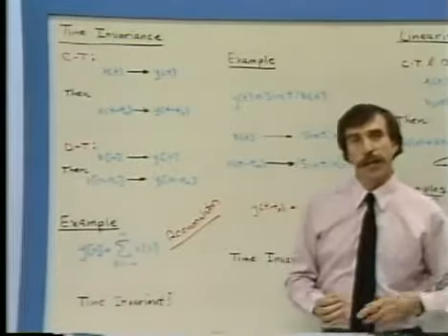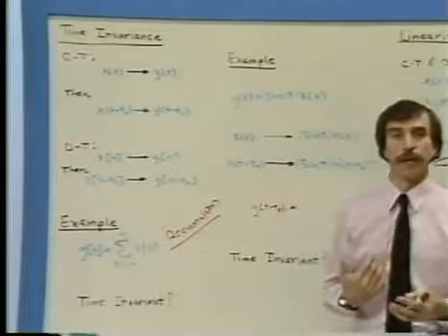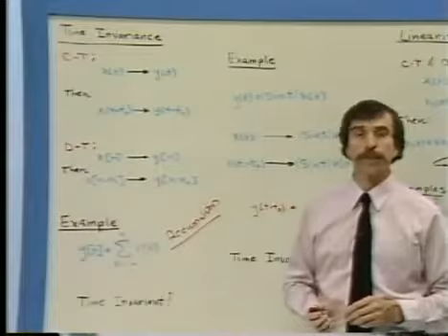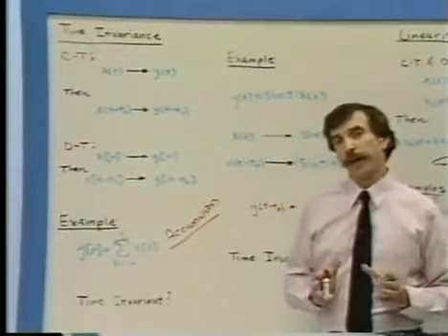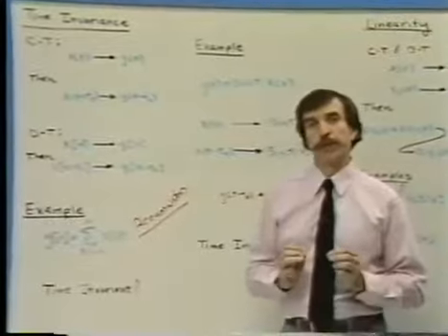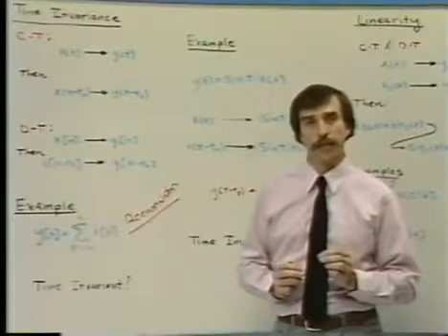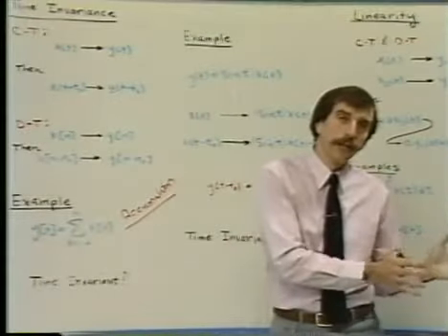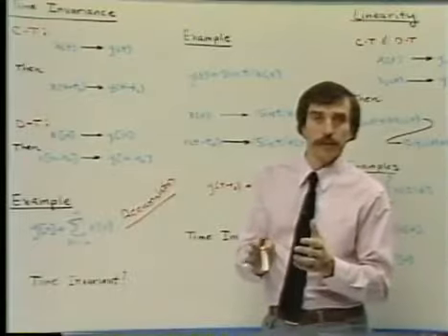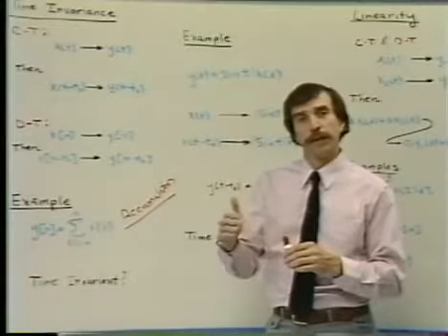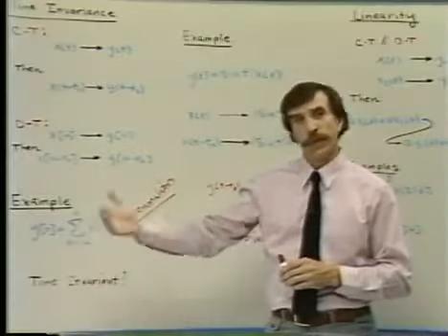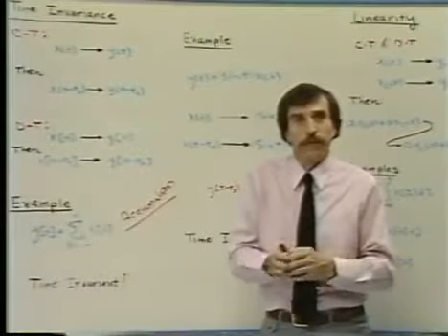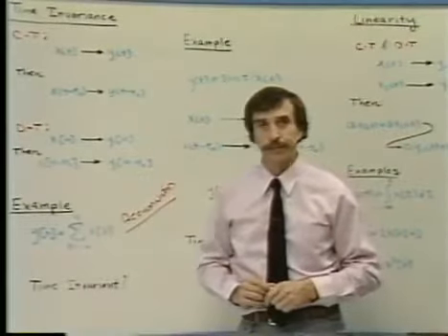The best way to establish that is to work through the equations and verify that it either does or doesn't satisfy the formal definition of time invariance. Informally, it makes intuitive sense that the accumulator is time invariant, because if you delay the values that you're putting into the accumulator, then the associated values that come out will be delayed by the same amount. The accumulator doesn't care really. If you shift the input, it'll just simply shift the associated output.